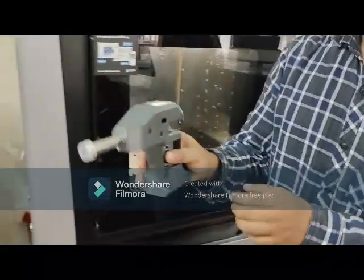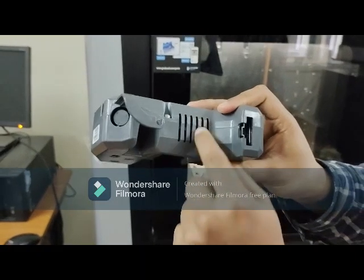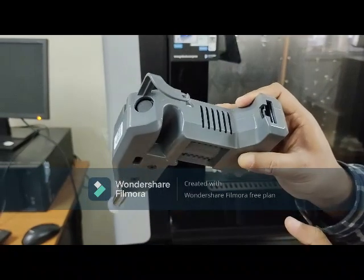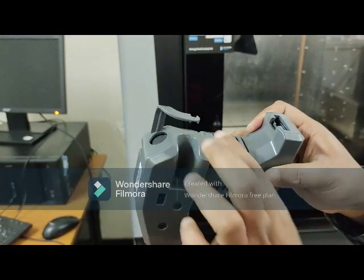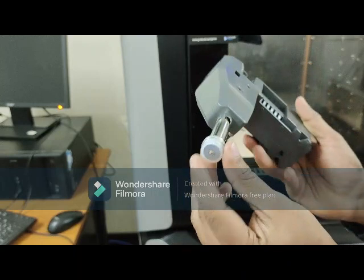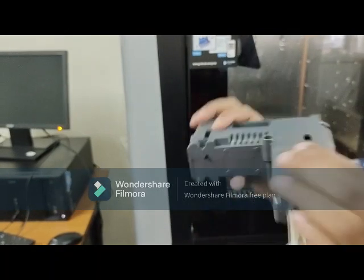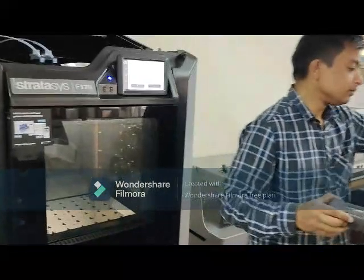So basically this is a PLA head we have here. This is the heater section. You can see we have some lining here. This is given to reject some of the excess heat. If the heater is heating above the desired condition, it will send this out to the atmosphere. This is the heater section, we have some rollers here, and this is the nozzle, the part where the material flows inside, and this is the nozzle tip, the nozzle head. This is used only for PLA material, and for the rest of the materials we are using the standard one.